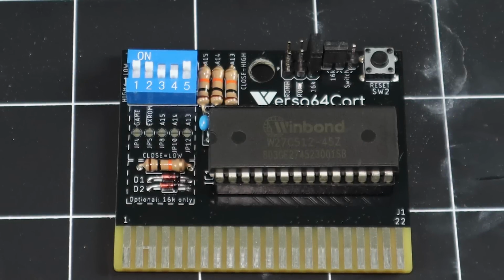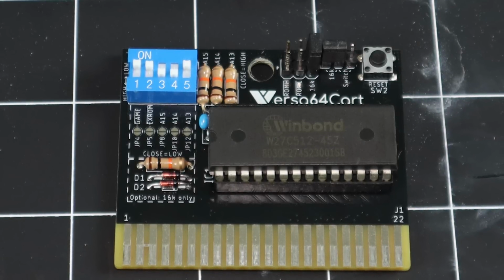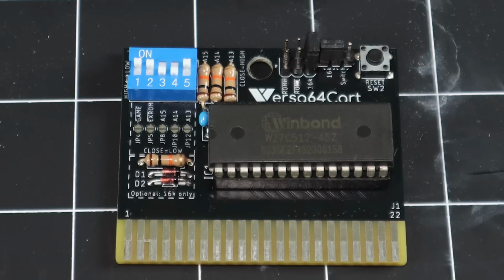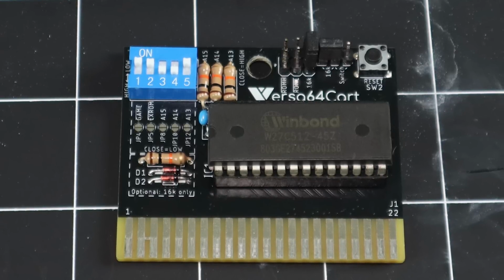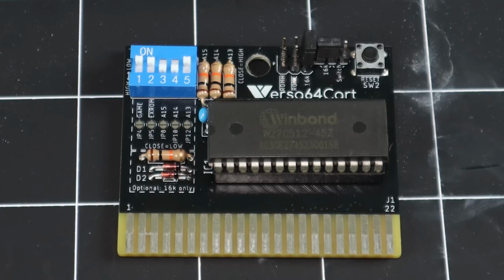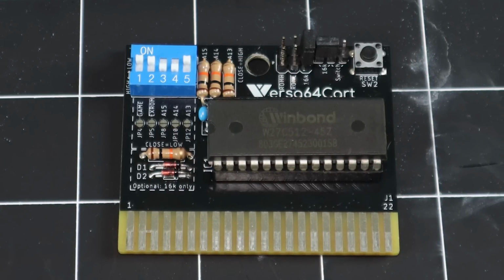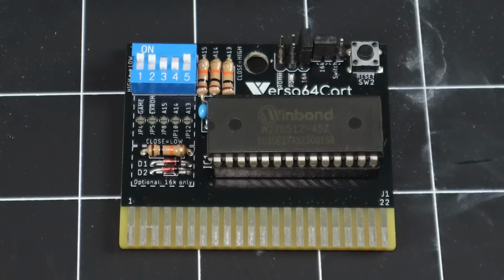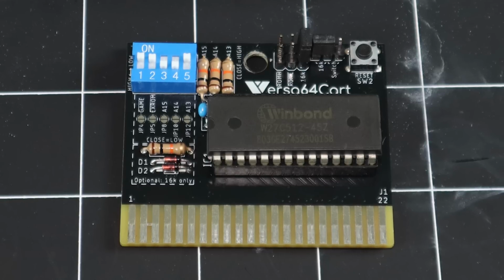One thing to pay special attention to is that the on or up position of the dip switch indicates a low setting and the off or down indicates a high. This is a little counterintuitive until you remember that the control lines are high by default, and to express that they're activated you must pull them low. The PCB silkscreen shows the correct switch positions, so it's best to just ignore what's printed on the dip switch itself.